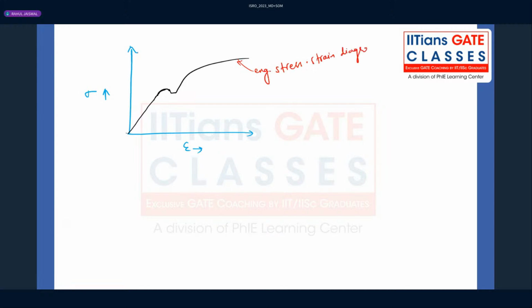What we are observing is the engineering stress strain diagram that we obtained from the original diameter. Whatever the original diameter was, we have considered it for calculation of the stress at individual points. See that all points are based on the original diameter. But generally, there is a deviation from this with the true stress strain diagram, something like this. It starts deviating from this point and continuously increases like this. So this is nothing but the true stress strain diagram.